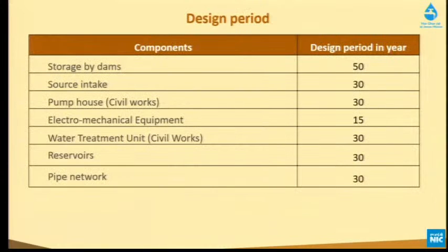Design period. Here I have put a design period. You can see that except for some electromechanical equipment, like the pumps and the electromechanical part of the treatment plant, my entire infrastructure, whether it's a pipeline, reservoir, water treatment civil work or pump house, has a design period of 30 years. When we design a system for 30 years, and I'm talking about the design life, if we maintain this infrastructure, the service life will be much more than the design period.